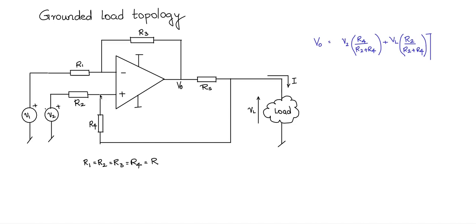So this is the voltage that is available at V plus, and that is multiplied by this gain, 1 plus R3 by R1, because V naught is equal to whatever the voltage drop across R3 plus V plus voltage. So that's why 1 plus R3 by R1. Then minus, there is the V1 component which comes to the output because that is going as an inverting amplifier, V1 into R3 by R1. So this would be the voltage equation.